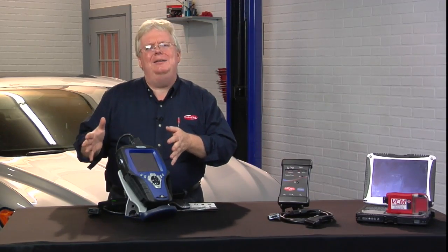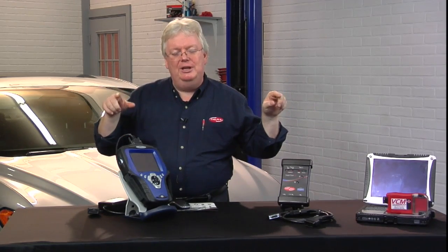Now, some things that can suspend monitors, and you'll never see them fully complete and give you good mode 6 data, would be problems in other areas that are related. For example, catalytic converter efficiency. Whether we set a P0420 or P0430 or not depends on a couple other components besides the catalytic converter itself. The O2 sensors, pre and post catalytic converter, have to be performing well before the PCM will trust them enough to go ahead and run the CAT monitor.